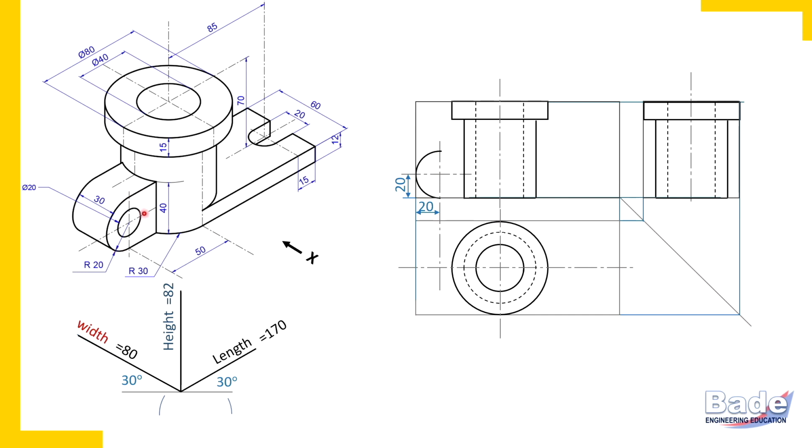Now immediately we can draw this circle also because it has the same center. For the circular hole, its opening is visible from the front, that is in the front view. Let's draw that opening of the hole also. So this is how we have completed the opening of the hole. Now this U-shaped block is attached to a cylinder on its cylindrical surface from its left side.